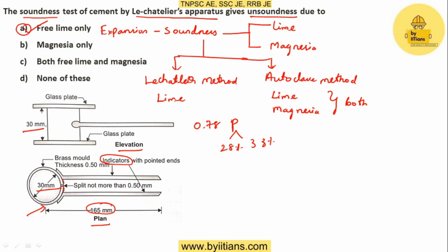Okay, after mixing this with water, we have to fill this mold. Then we have to immerse this whole setup in water at a temperature of 27 degrees Celsius to 32 degrees Celsius for 24 hours. Okay, after 24 hours we have to take this out, clean the apparatus, and measure this distance.